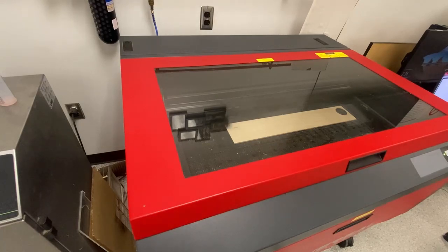All right, as you can see now, it's doing the rasterizing step. So this is what I meant before when I described rasterizing. It's going back and forth and only pulsing the laser where it needs to cut. So right now it's only doing the small ends, and now it's got like four pulses that it's going to do for a certain amount of time. And obviously it knows what it needs to do, and it'll go back and forth and rasterize that whole image.